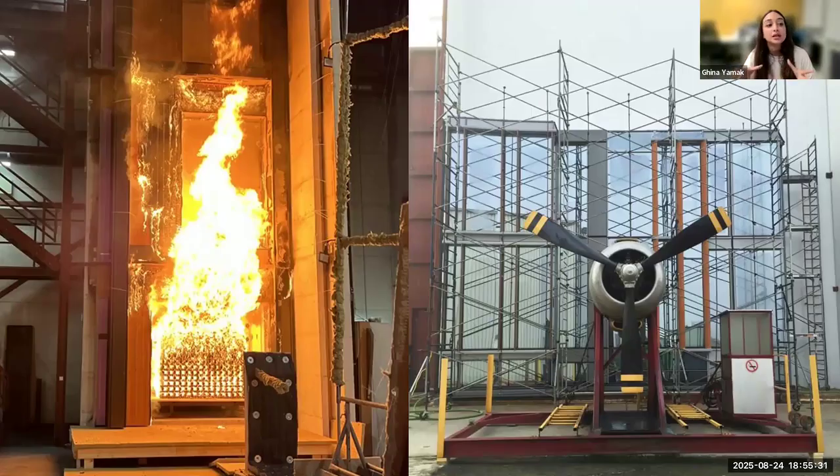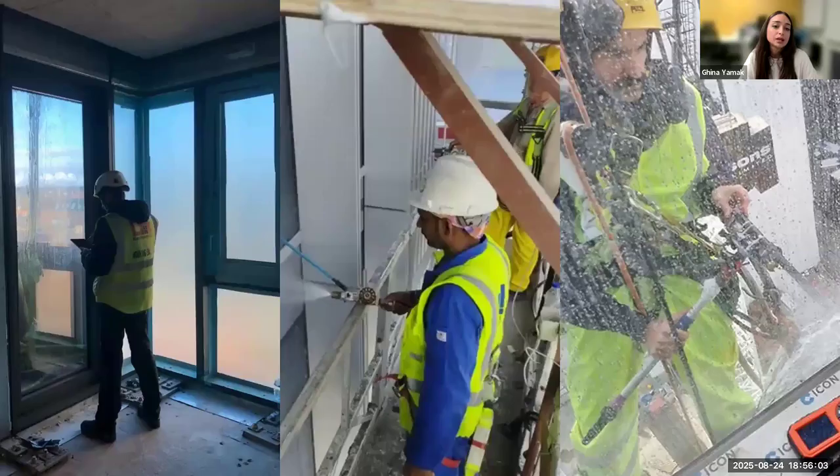So they design the facade, they manufacture it, they assemble it, and they take it to a testing agency, and they actually put fire on the facade and start counting for how many hours this facade can take. Is it 1 hour rated, 2 hours rated, and so on. So fire tests are one of the coolest, I would say. Wind and air tightness is also one of the cool facade tests that can be done, with the rain.